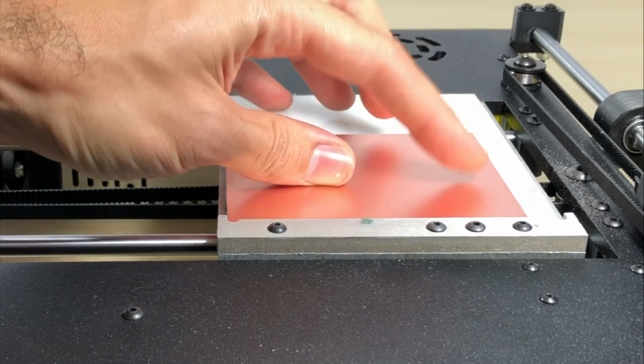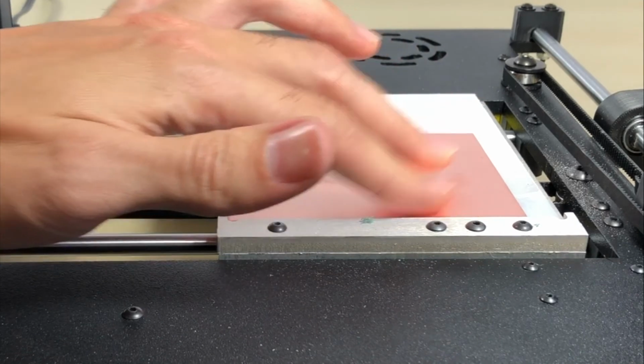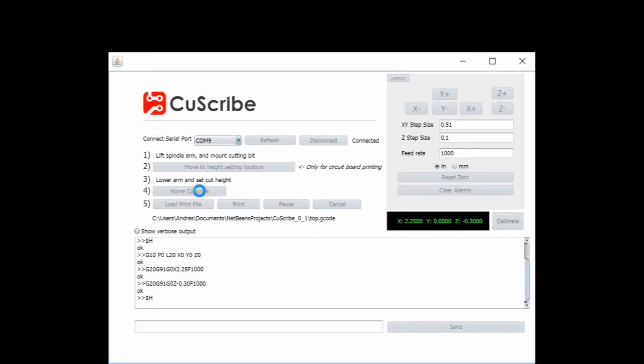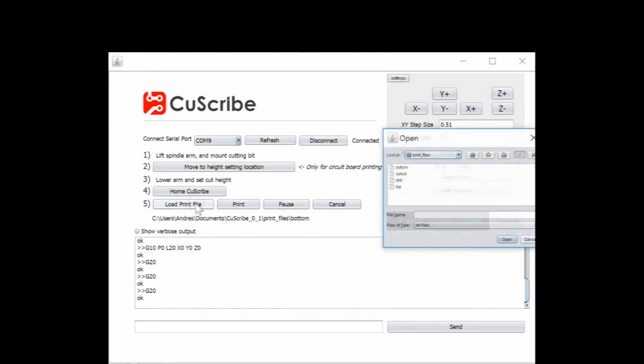For the top traces, we can skip setting the height and changing the tool because we will be cutting the same shallow depth with the same tool. After homing, we load our top trace file, turn on our vacuum and spindle, and begin our print.